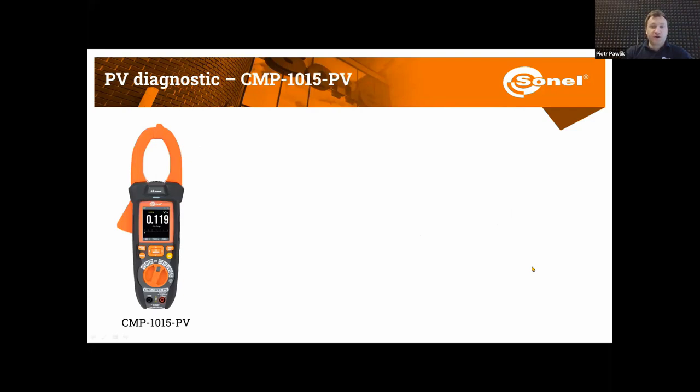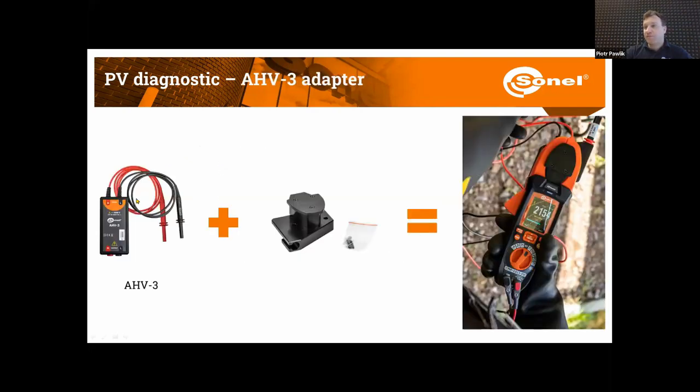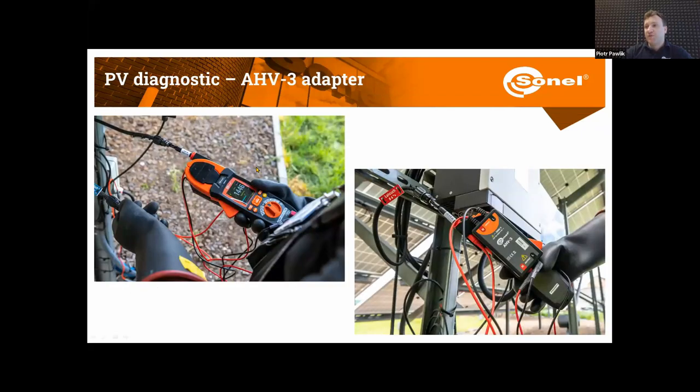We can connect it to different multimeters or clamp multimeters. This one actually has a holder which we can put in the clamp of the multimeter, and we can use it like this. This way, we can get values of even up to 3,000 volts. So that's just some useful adapters.